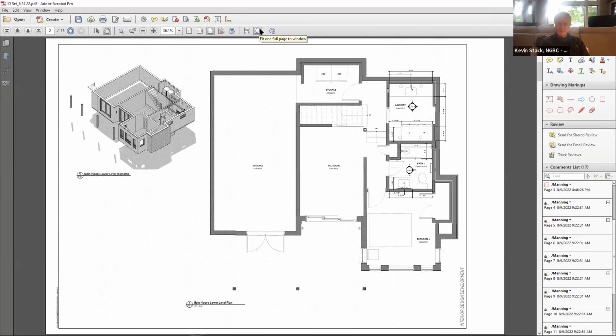So we're close. Also, I'm showing kind of a 2x4 framed out wall with 1/2 inch finished face inboard of that poured concrete, but I don't know what kind of insulation you need there from the interior. It might not be accurate to the closest inch or two. We might be able to grab a little bit more depth there, depending on how that whole thing is insulated. Planning on 3 inches for an R15 on the interior of the concrete wall? Preferably, because if we're going with natural stone outboard, Diana, we'd like to apply that directly to the concrete if possible. But certainly we could. Yeah, we need the backer board.